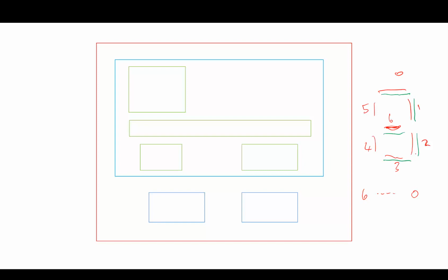And because it's active low, that means a 0 bit will turn it on. So we want segment 0 on, segment 1 on, segment 2 on, segment 3 on, then we want segment 4 off, segment 5 off, and segment 6 on. So this pattern here would draw a 3 on the hex display.